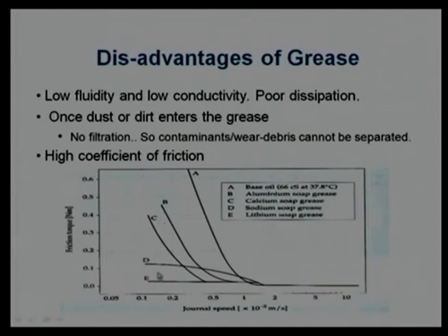With the change in the grease, we are seeing different behavior. Their load carrying capacities are different, and the lithium based grease is showing very high load carrying capabilities, as well as more or less the same constant friction force.